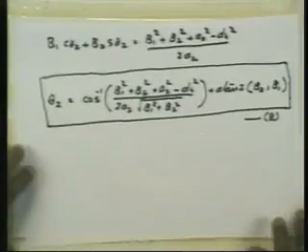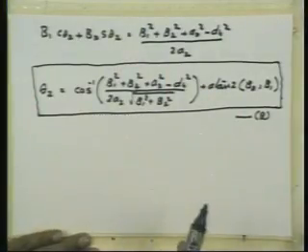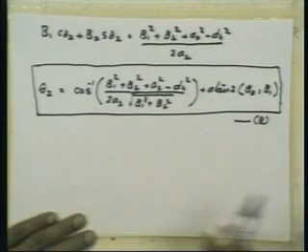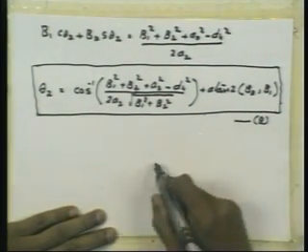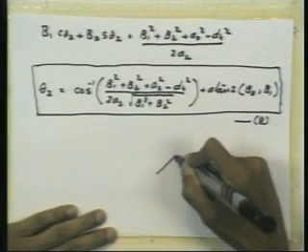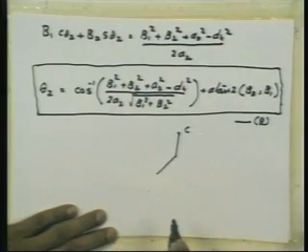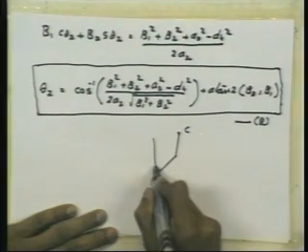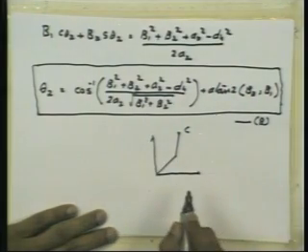So if you do that, then what transpires is the following. This comes from the cosine rule, which is used when we know 3 sides of a triangle. We see the manipulator like this, let us say the elbow up position. This is the point C. This is some reference frame in which we are now having these projections.